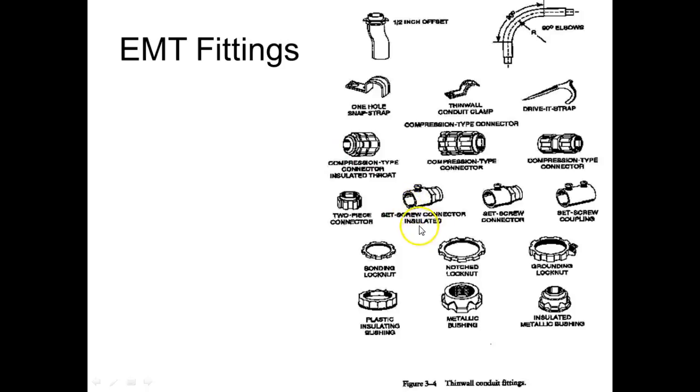These are more expensive. You'll see these used all over the place. These set screw types, what you do is you just have the conduit slide into it, and you tighten down that set screw. You see these used a lot in commercial applications. They're cheaper because you got...